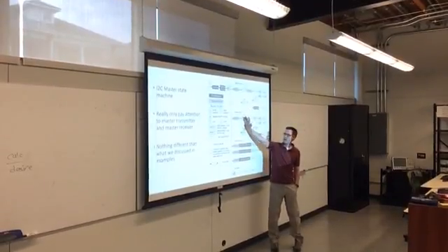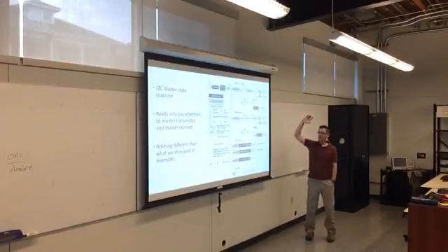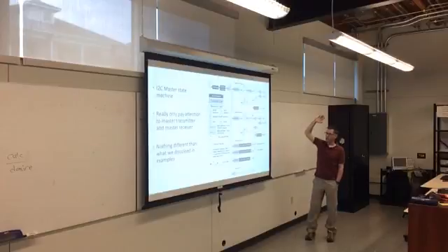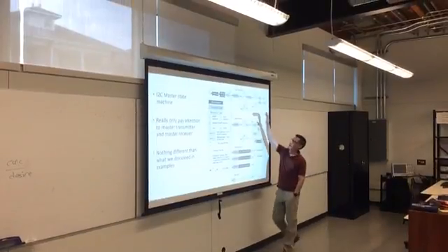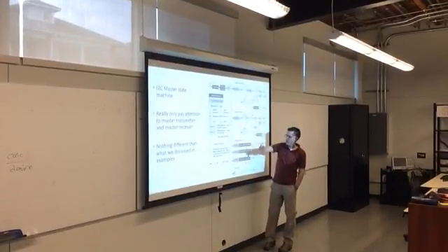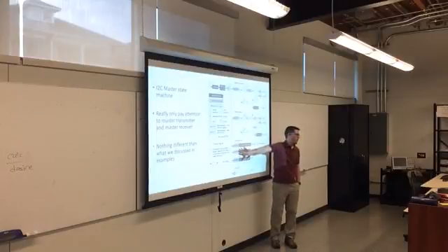It's a big state machine, but you can ignore a third of it already. So generally, transmit, here's receive. Here's what happens if you lose arbitration. You're going to be the only one talking to us, so you don't care about this. So immediately, you can already just kind of get rid of half of it.